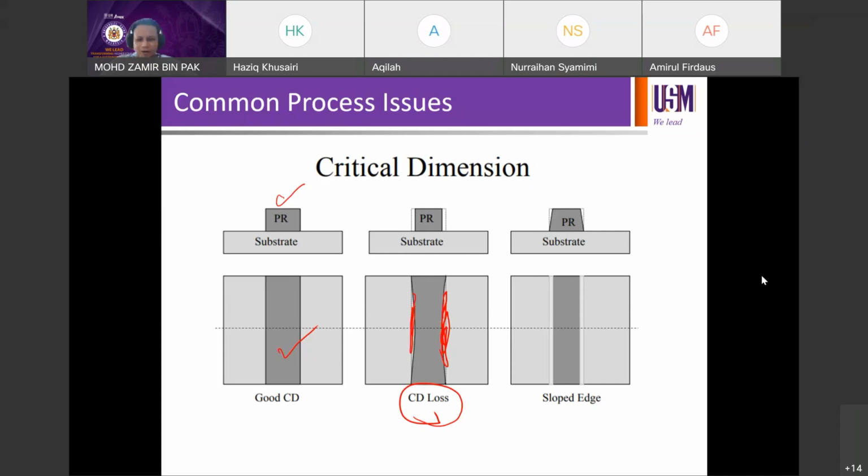Kavina, what would you do? You are the person, you are the engineer in charge of this layer. You're supposed to get 100 nanometer, you're getting 125, you're printing lines, you're suspecting the energy dose to drift. Still figuring out, okay? Anyone else? Mac, lama tak ada suara Mac.